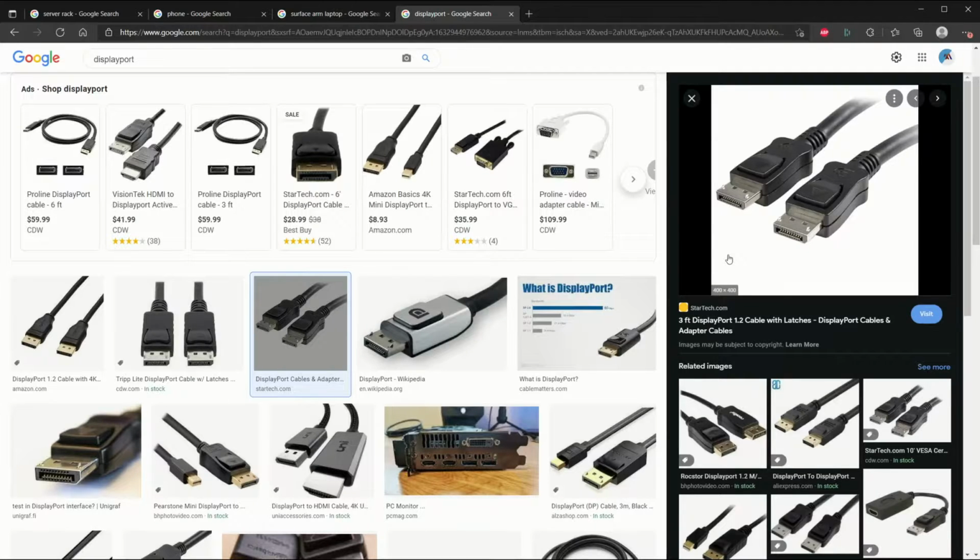So basically, I have this cable that I was talking about before. I have two cables, actually. One is the HDMI to USB-C one that I was using to connect my monitor to my HP Omen computer there. But I have this other one for connecting my Mac, and in order to get 144 hertz at 2K resolution, which is what my monitor is at, I need a DisplayPort. And DisplayPort is more compatible than the HDMI 2.1 standard, because just because it has an HDMI port doesn't mean it's HDMI 2.1 compatible. So DisplayPort is another option that can be used if you want a higher frame rate and stuff. It's pretty common on monitors, TVs, and graphics cards for computers also have DisplayPort. Depends if it's out or not, but we won't worry about that now.